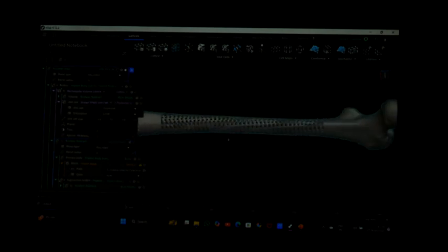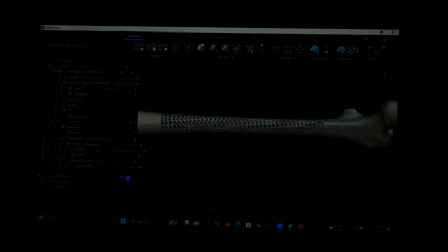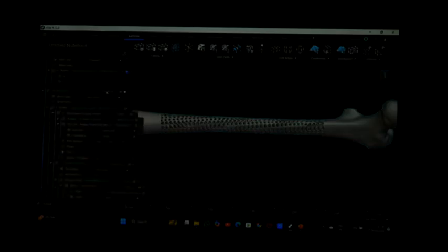So this is how we can get it. Again, we can convert this into an STL body, but the processing time will get more. That's why I am not converting here. That STL body you can use for manufacturing. That is how we can use topology optimization. And weight saving, last thing, then we can wind up. Weight saving we will see. Lightweighted body means this one, right? Combined body, bone final.